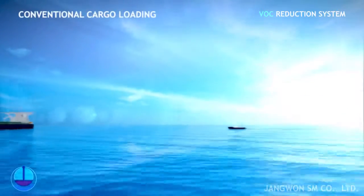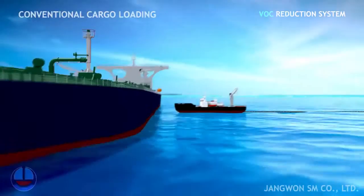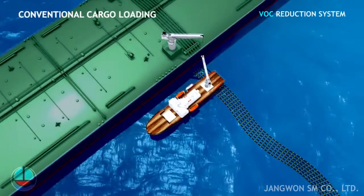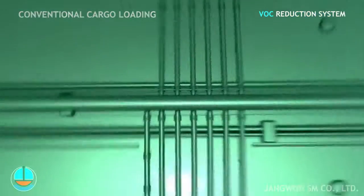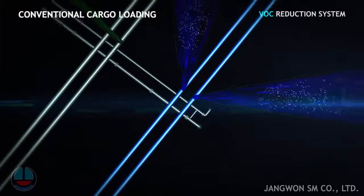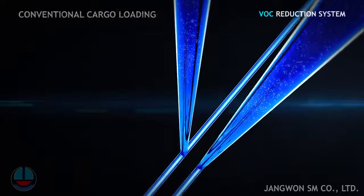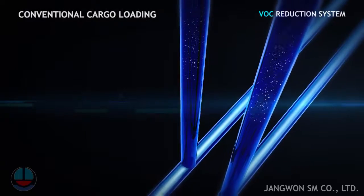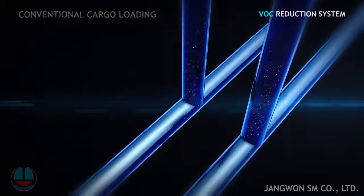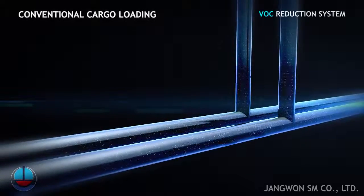It is known that vacuum condition is made in the upper parts of cargo drop lines, due to insufficient back pressure during the cargo loading operation on conventional oil tankers. And the vacuum condition forms a huge amount of VOC bubbles, the majority of which are condensed by hydrostatic pressure, but the rest still remain in bubble type in cargo tanks, and ultimately vent to the atmosphere all through loading and transportation periods.